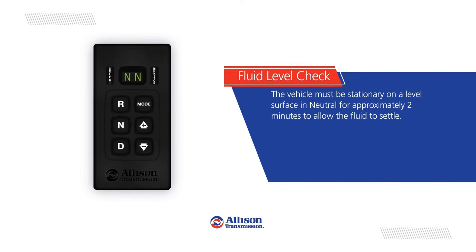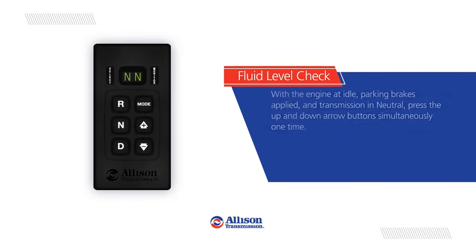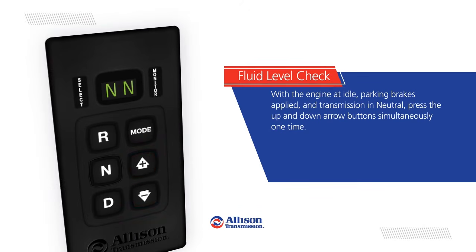The vehicle must be stationary on a level surface in neutral for approximately 2 minutes to allow the fluid to settle. With the engine at idle, parking brakes applied, and transmission in neutral, press the up and down arrow buttons simultaneously one time.